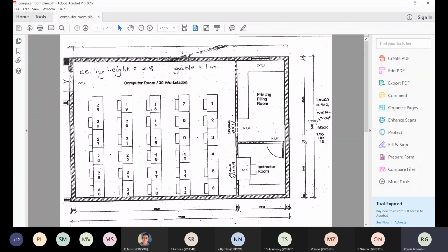Now I can just use the same value for the external walls. There's no need for me to go and adjust, because although it'll be slightly less, a couple of bricks, there's no need, because we're already allowing for wastage and so on. So I'll use the same value as the face bricks for the external,